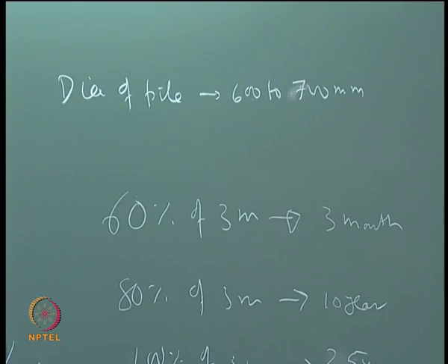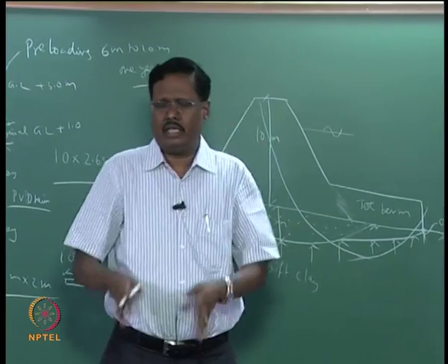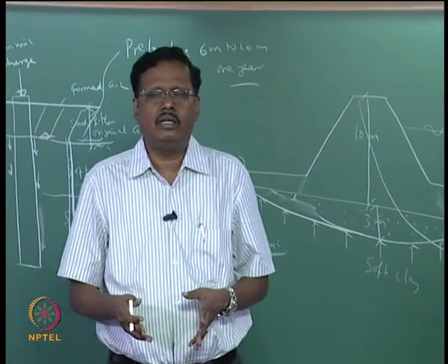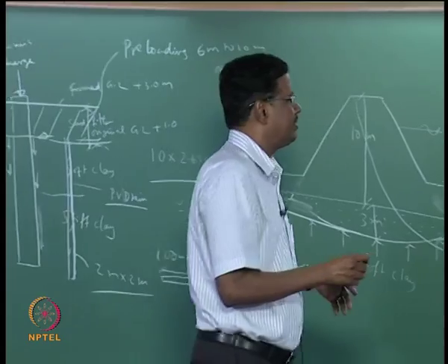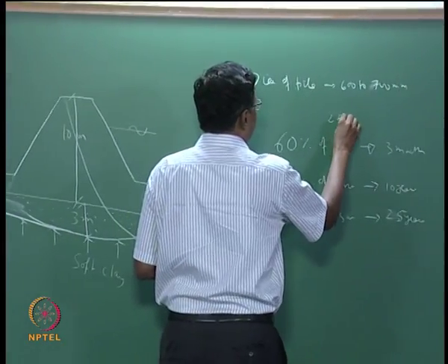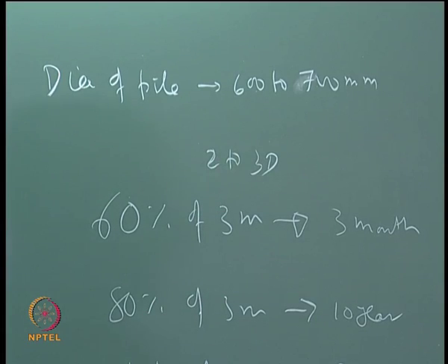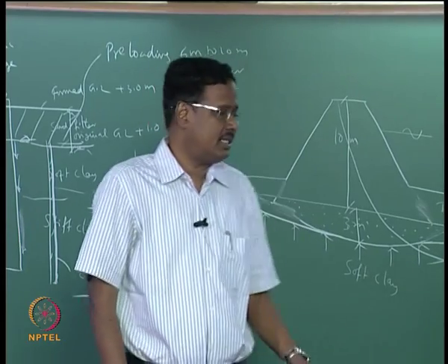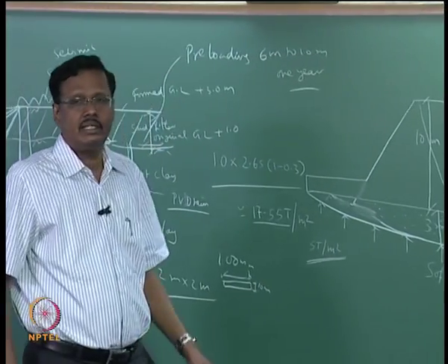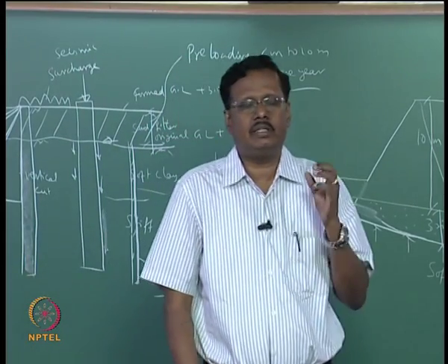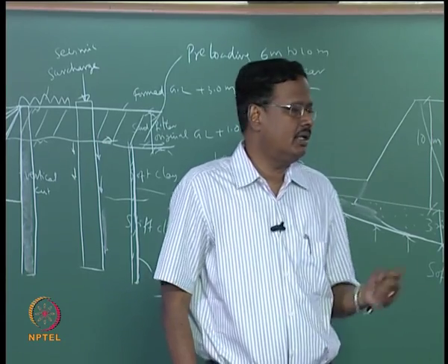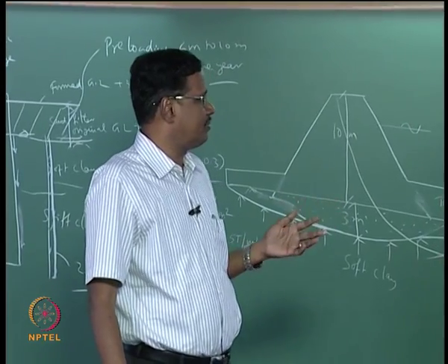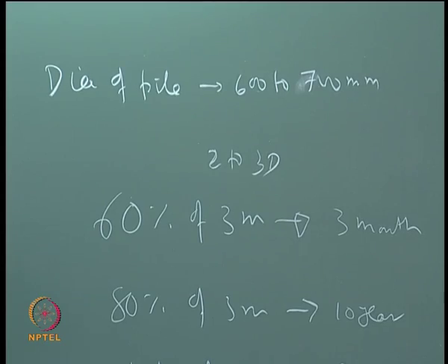So you just lower the casing pipe with the bottom opening, once you drive all these at very close spacing, normally 2 to 3 times the diameter spacing, and you replace the soil in that location by dense sand. So it acts like a filter medium also, the sand itself will act like a filter medium and it is replacing the existing soil and it is compacting also. So the volume of replacement may be about 10 to 15% of existing soil.